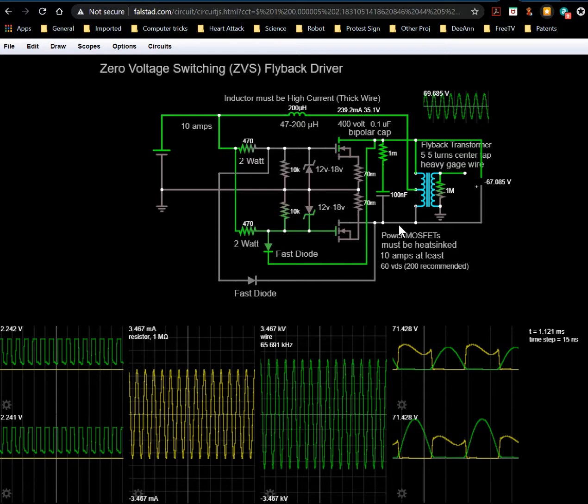So they keep switching roles, and because of that, the capacitor keeps switching, and that happens to coincide with where the capacitor changes its charge direction, because its voltage is always changing. But that's why this waveform always looks positive. So it's positive 70 volts here and positive 70 volts here, but it's because this thing is continuously being switched back and forth. And that's what's critical to understand, and makes it hard to understand, because it's zero here, but when this voltage is low here, it's high here, okay?